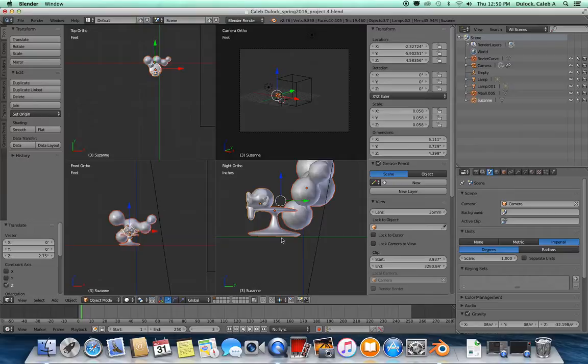Okay, so now what we need to do is, this is just a review from one of the previous exercises with the project, where you need to review all your models in your design and make sure that you have only mesh objects. So again, if you have any objects floating in your design that are made of curves, metaballs, surface NURBS, or text from Blender, then you will need to convert them into mesh objects.